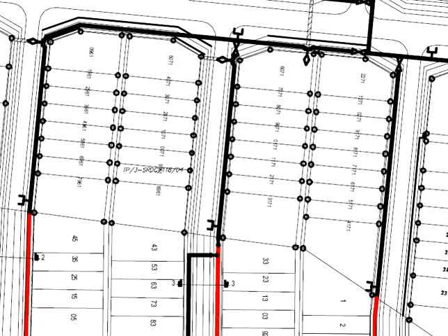However, it doesn't work this way in reality. Ultimately, after the development, the developer will have to hand over the water reticulation systems to the water supply agency without any cost. There will be a defect liability period of 12 months.